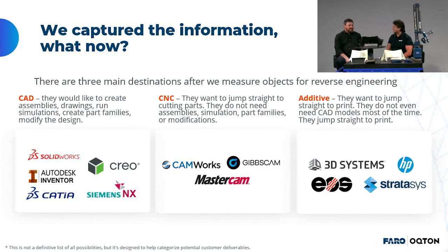So you actually want to scan it, correct its measurements, and make a perfect part from it, and then manufacture good parts from there. This is just pointing out that there are reasons why you would want as-built and design intent. Either or, and on the last example there, you can use both of them. There may be parts of the part you want to be exactly like the existing condition, but then make changes to it to add some design intent. And that's what the why not both is pointing out.